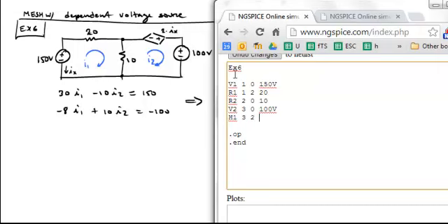And then we have to specify what is the current that it's dependent on. In this case, I don't specify 2 nodes. I actually specify a voltage source through which that current flows. All right, and if I recall, you couldn't say, well, let me just show you what we're going to put here. We're going to put V1 because Ix is current flowing through V1.